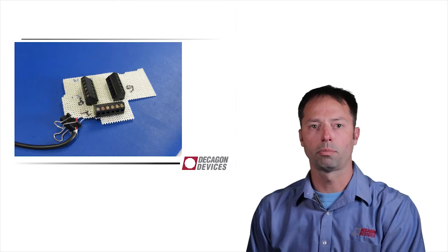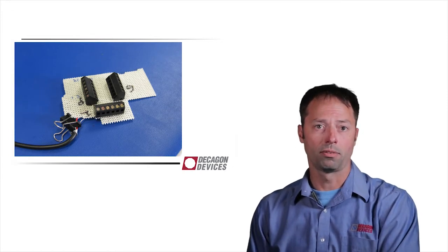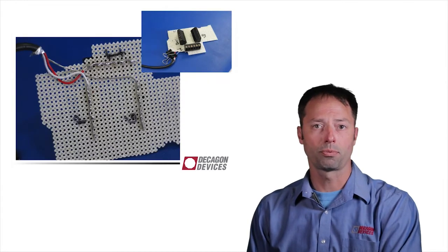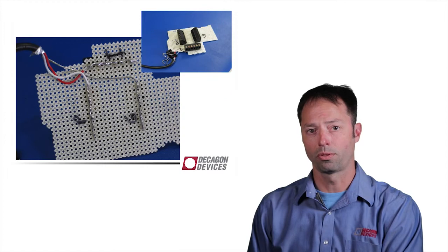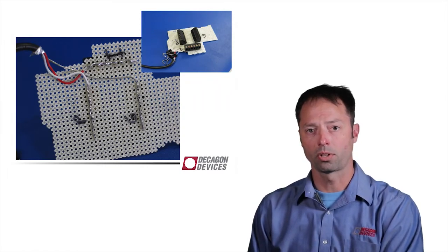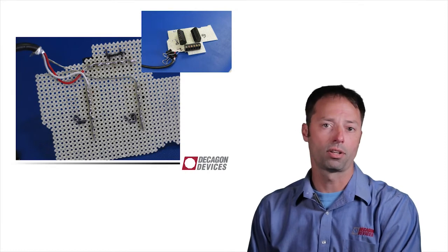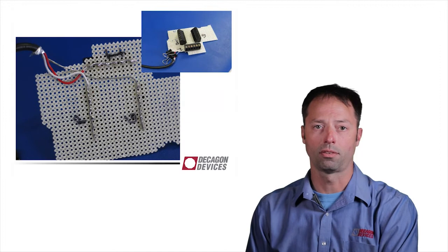This is just an example of a fairly simple bus that I constructed. There's nothing wrong with a homemade bus. We'll talk about a few guidelines for making a good one. This one, you can see it's just got 3 terminal blocks, and they're all soldered together with the white going to one terminal, the power line going to one terminal, the red data line going to another terminal block, and then the ground line is the third block.